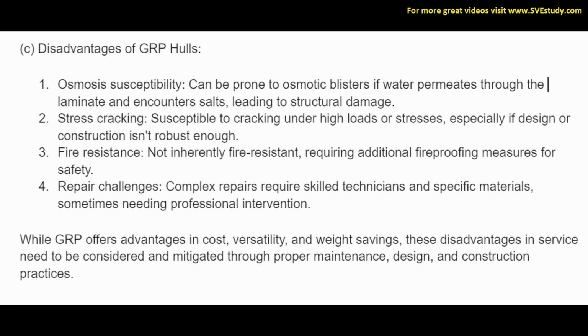3. Fire resistance. Not inherently fire resistant, requiring additional fireproofing measures for safety. 4. Repair challenges. Complex repairs require skilled technicians and specific materials, sometimes needing professional intervention. While GRP offers advantages in cost, versatility, and weight savings, these disadvantages in service need to be considered and mitigated through proper maintenance, design, and construction practices.